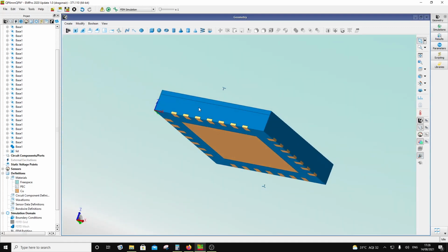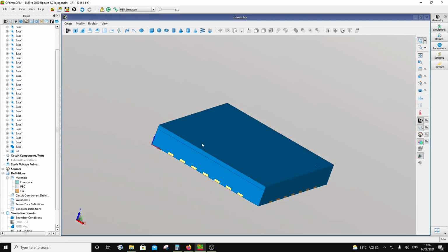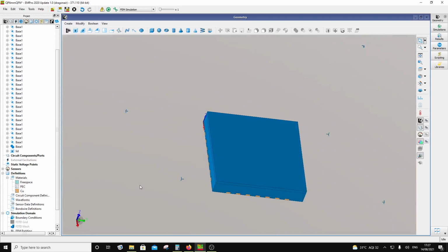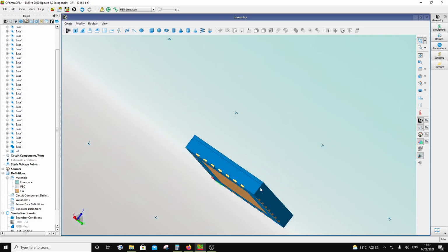So what it means is that you can coat this lid with a metal, and then have vias going from the top to the ground plane. So basically, it acts like a cavity. So this will protect it from EM radiation or EM pulse, whatever electromagnetic pulse you see. You fry the circuits with this EM pulse, like in the movie The Matrix, right? You could fry everything with the EMP. So that will not happen to your circuit if you surround it with a metal cavity. So that is called castellation, right?